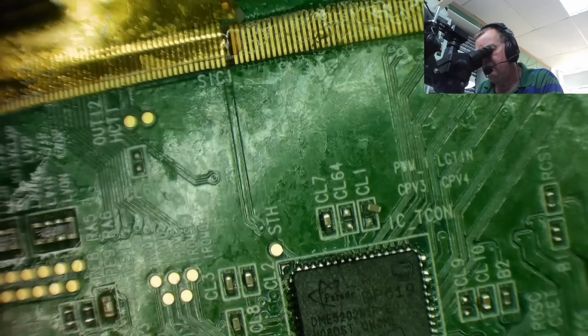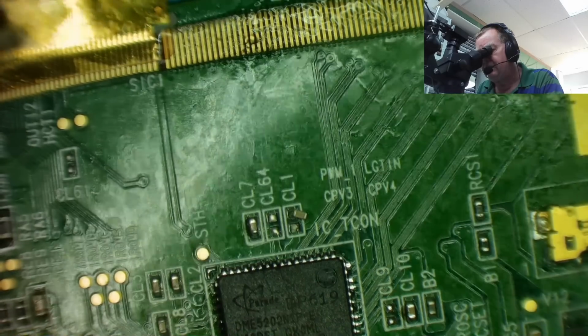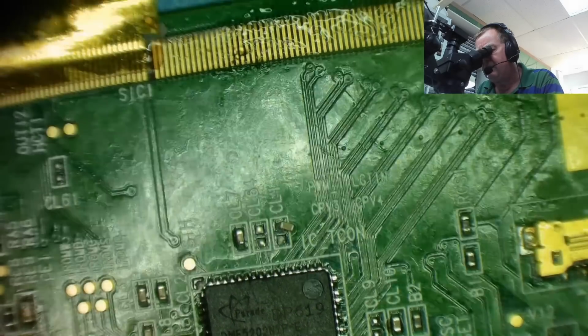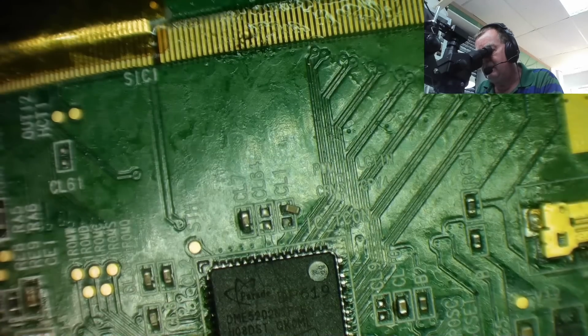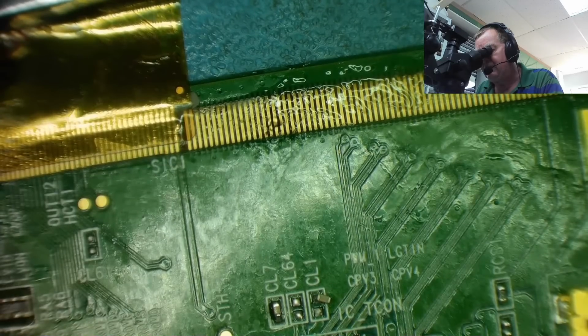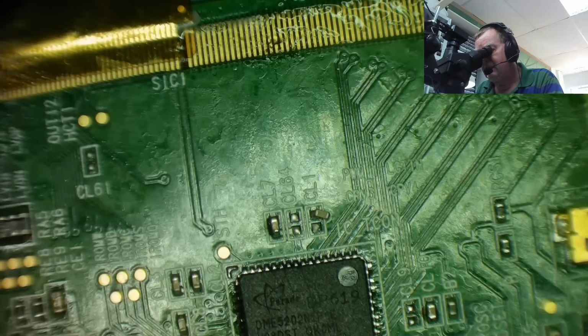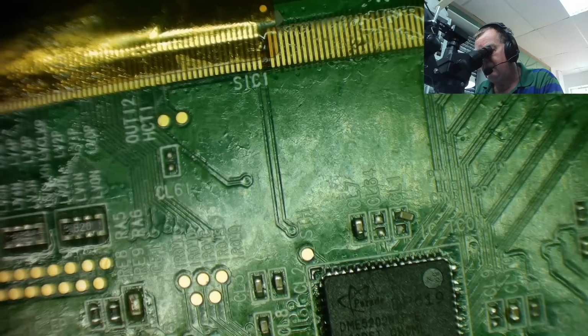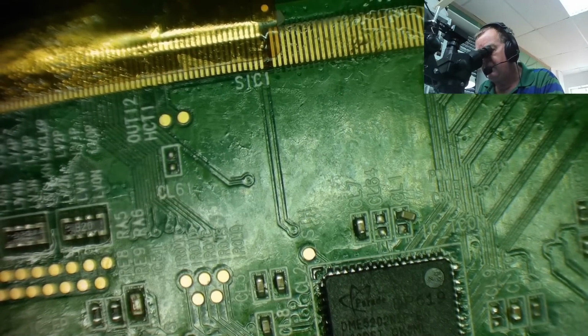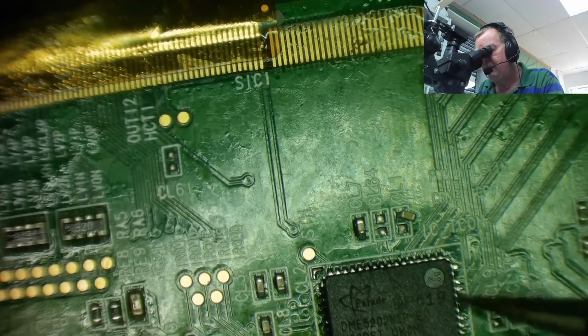It's lined up good. Looks like there's a few pins that didn't take any solder. But I'll try to reflow it first with the hot air. If I'm not happy, I'll come back again, I think, and have a go with the solder. But there's maybe a couple down here. But I'm hoping there's enough solder on underneath to do the job. Remember, there was already some solder on the pads as well.